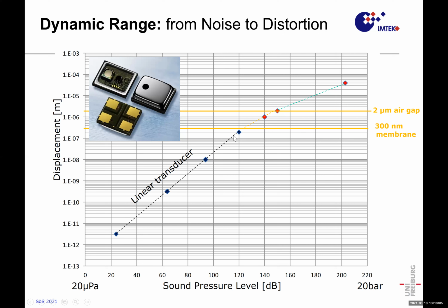And of course, you can move the diaphragm further. Then it's highly nonlinear. And this happens with pop noise, wind noise, which is extreme. So 140 decibels you can have easily at low frequencies like a door slam or clapping with your hands. This does not harm your hearing because it's low frequencies. If you have the same sound pressure level at 1 kilohertz, you get severe issues, of course.